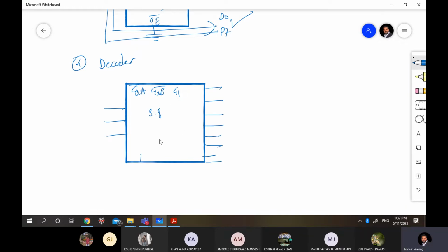Getting it? So this is one more IC we are going to use, that is a decoder, and 74138 is the IC specific name. Now, these 3 pins are used for enabling. The active low pins I will connect to the ground, and the active high pin I will connect to 5 volt, so that this IC will be turned on. To this we will give 3 signals, and depending on that it will create 8 signals. I hope you understand how this 3:8 decoder works. Yes, everyone knows how a 3:8 decoder works.